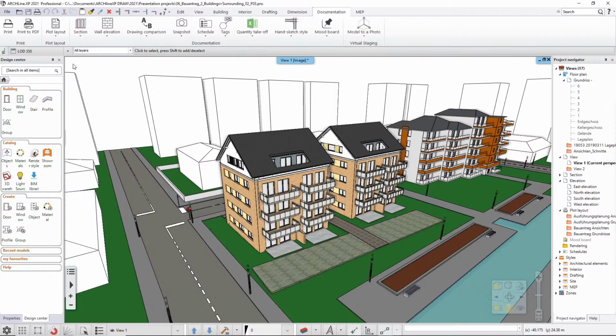By default, you can see LOD levels readily selectable from this list as LOD 100, 200 and so on up to LOD 400. And the default setting in ARCHLine when you start designing is LOD 350, as you can see it here. Now this is good for all the planning design, the details and everything that you would like to see and create intersections, detailed drawings, situation plans, detailed construction plans and so on. So this is the default setting.